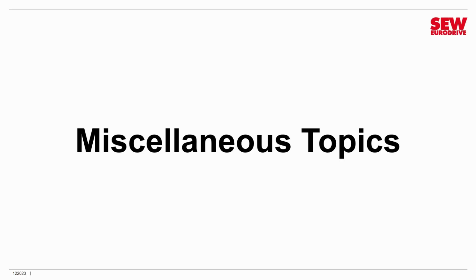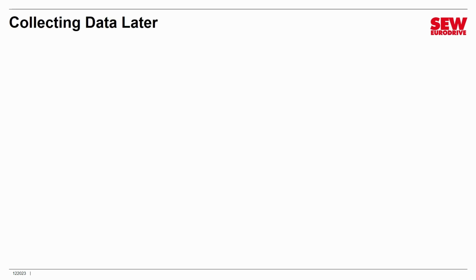We're almost done with this session, but there are a few miscellaneous topics I want to cover about the scope before we sign off, so let's cover these. I've mentioned several times that you can set up the scope to collect data over a long period of time, and you don't have to leave your PC plugged into the VFD. I'm going to show you how you set that up right now.